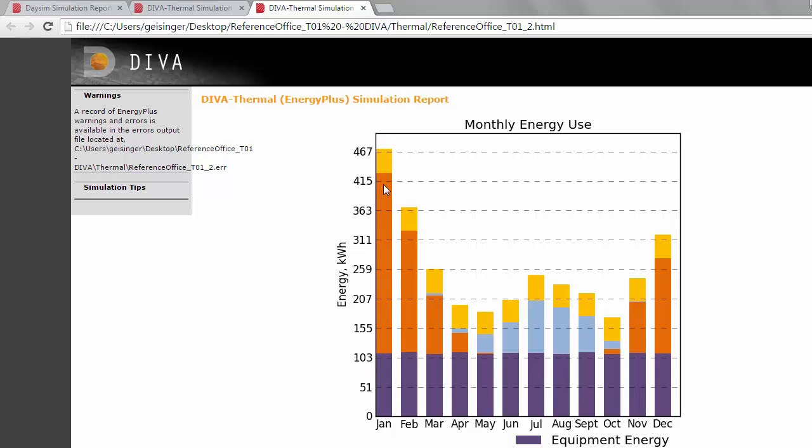month of January, our total energy use stays the same, but the balance between lighting and heating is going to be a little bit different. So if I do another comparison, if I just go quickly back to my initial energy analysis and look at January, the total energy stays the same for that month, but in the initial iteration there's more heating and less lighting. Now in my current iteration, I clicked on this current one, we have more lighting because our lighting controls have decreased in performance, and our heating energy is a little bit lower because our load is lower, because we're using a little bit of the additional electric lighting energy for sort of borrowed heating.